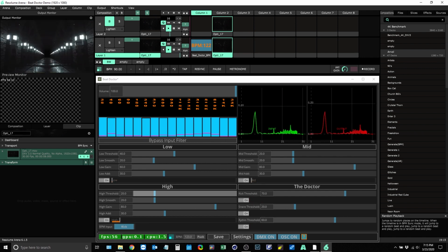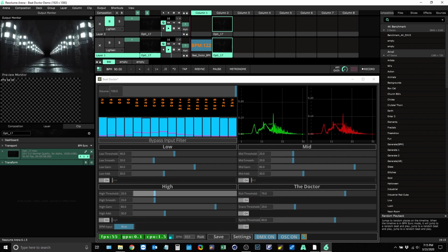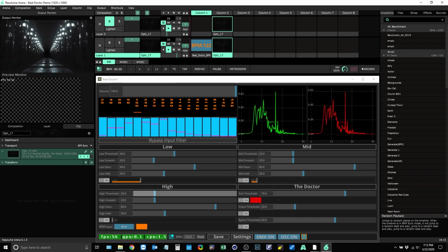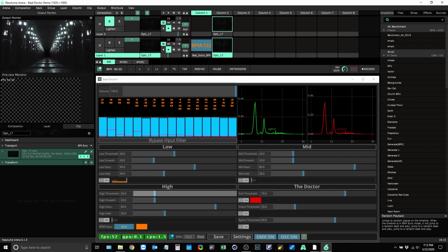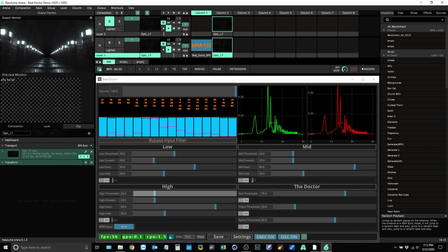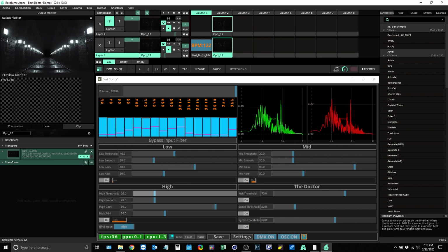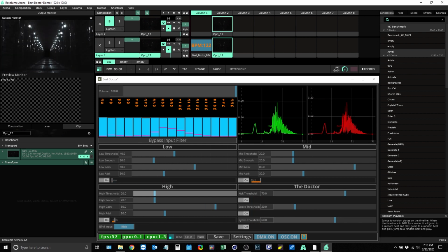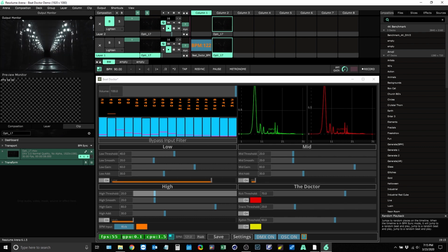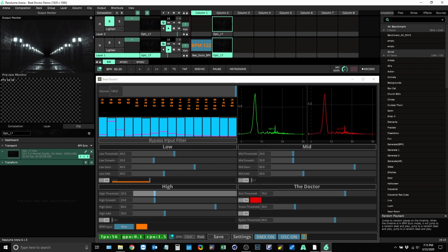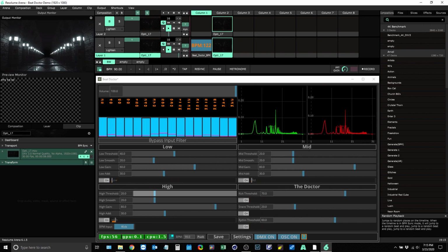But it's always good to have quality hardware when you can get it. So yes, this will work if you're plugging a cell phone into your 1/8" jack on your computer. Is it recommended? That's up for you. The way I always use this is at front of house. We have our front of house audio engineer, and I politely go up to said engineer and I say, "Excuse me, sir, can I please come out of one of your matrices or your auxes?" And there's never been a time I've been told no. They've always been super friendly about that. So they'll typically run you a stereo pair of XLRs from their console back to wherever your video station is. And from there you can have whatever audio interfaces you like.